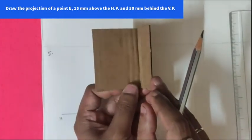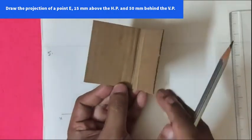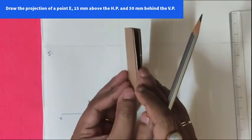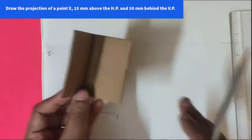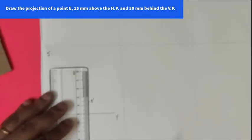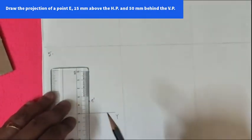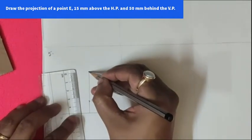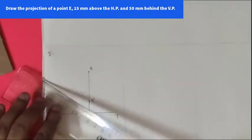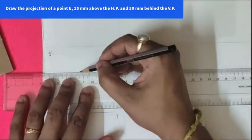Now you have to rotate the plane. So on rotation, what will happen? You see, this 50 mm is projected where? Above the XY line. It goes up above the XY line. So again from this, you measure a distance of 50 mm. Join this line. This will be your top view.